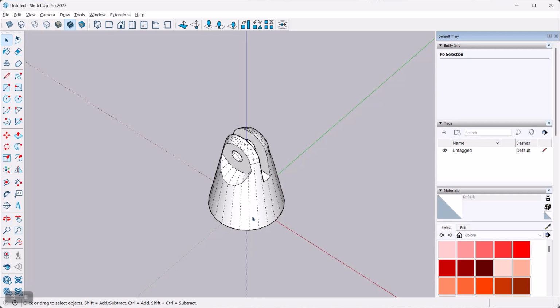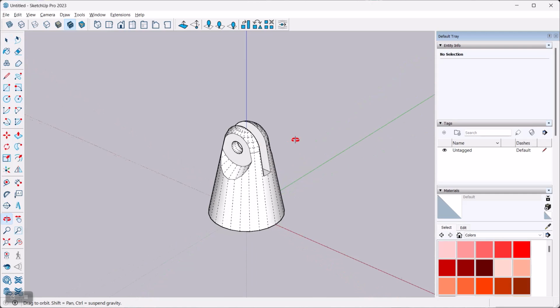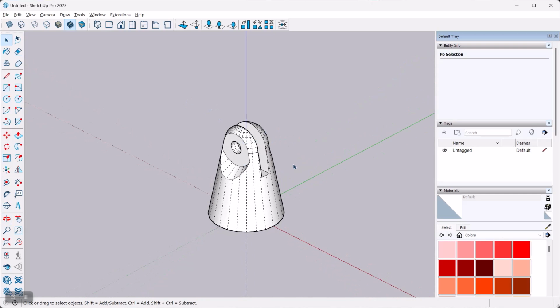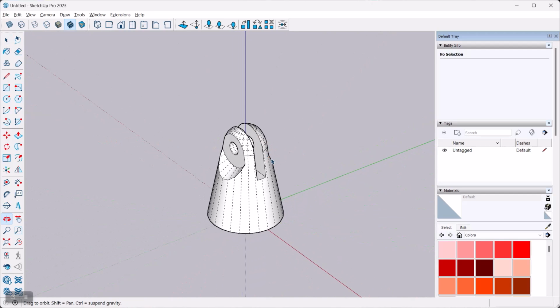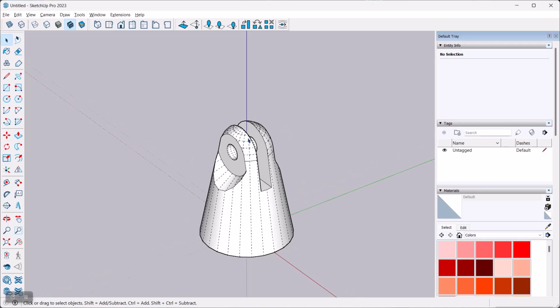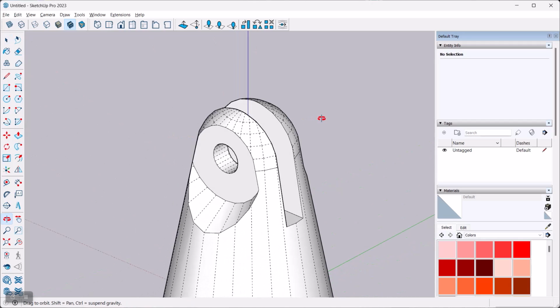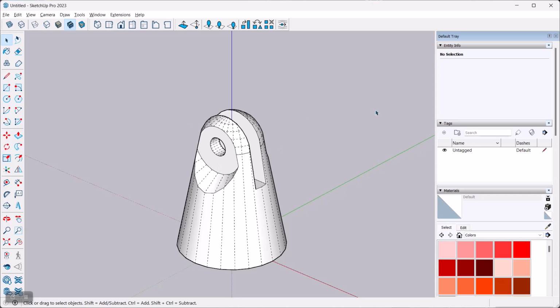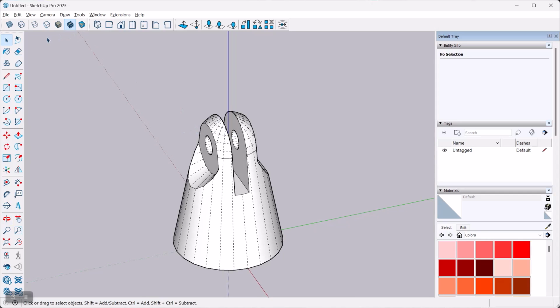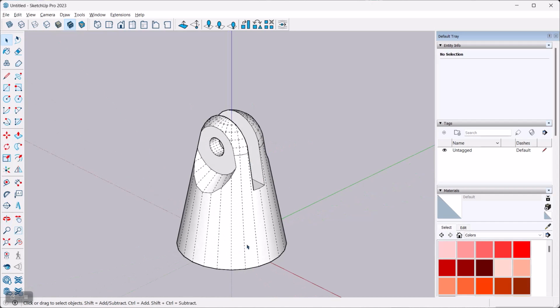Ultimately then, of course, I would do the same, maybe a few cylinders down here for these bolt recesses. And then I'm good to go with this. There's a bit of a scale thing happening in SketchUp. So if this is a tiny part and you need to use the same approach, then it helps to scale things up first to a reasonable scale, several feet, meter, whatever, and then do the solid tools operations to subtract, and then you can always scale it back down.